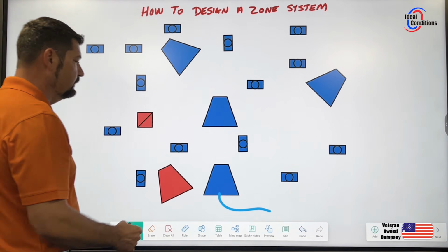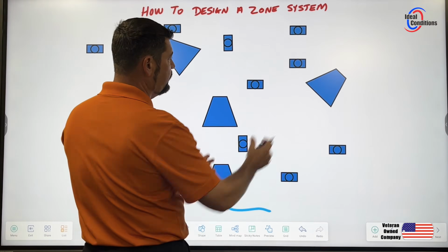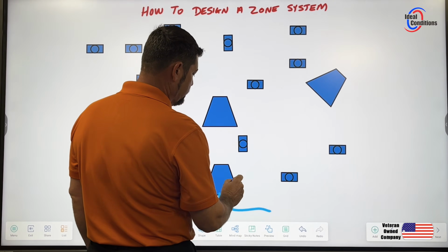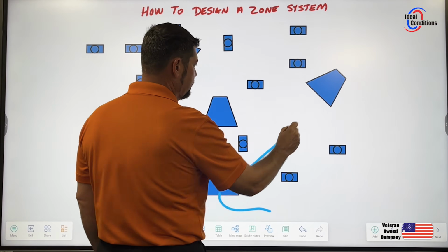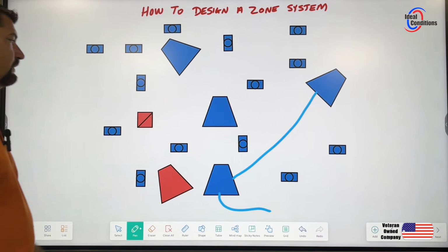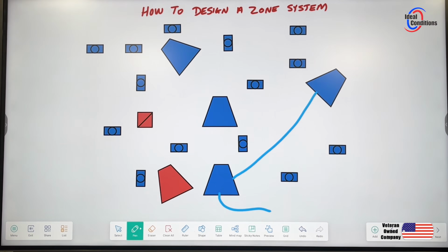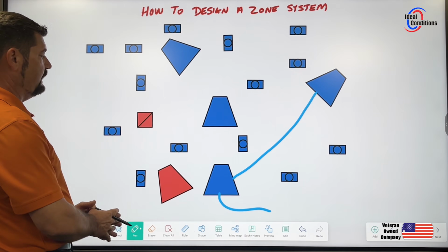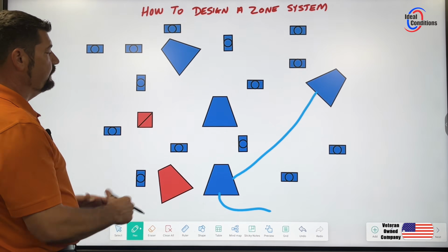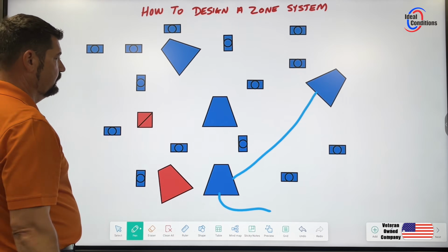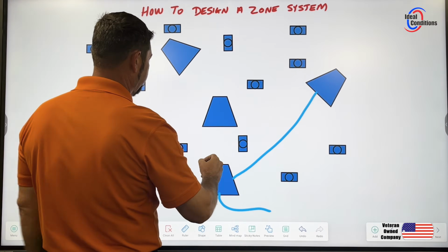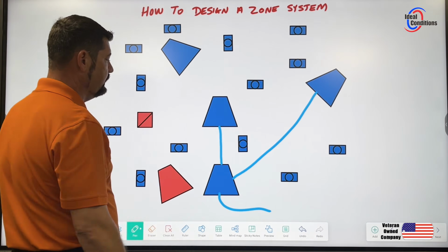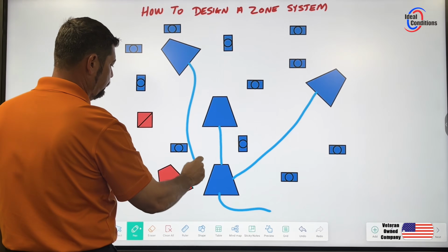That supply coming in, it looks like everything over here doesn't really have to be altered that much. So getting right into it, I'm going to say that my trunk lines are the first thing I need to map out, not the takeoffs. Okay. So if I wanted to have a 3-zone system, then I would take advantage of these mixing boxes, and I would say I'm going to take this out of here, and I'm going to take this one out of here.